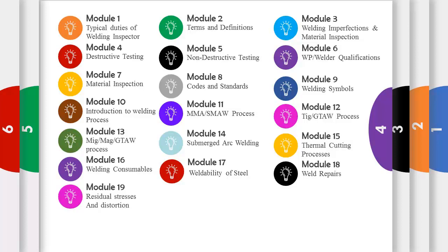When this presentation has been completed, you should be able to identify the reasons for and prevention of residual stresses and distortion: development of residual stresses, what causes distortion, the main types of distortion, factors affecting distortion, prevention by presetting, pre-bending or use of restraint, prevention by design, prevention by fabrication techniques, and corrective techniques.